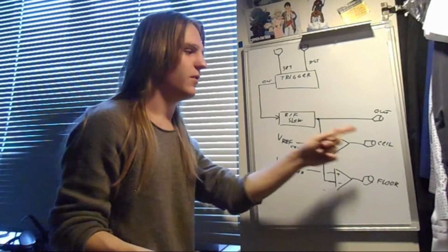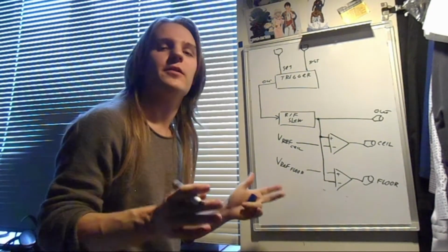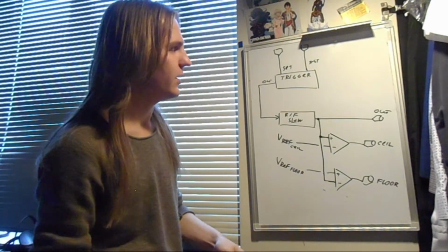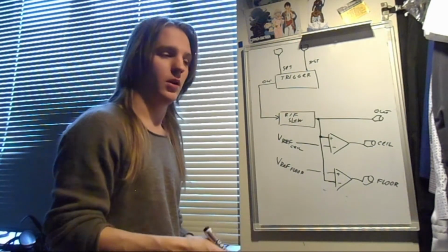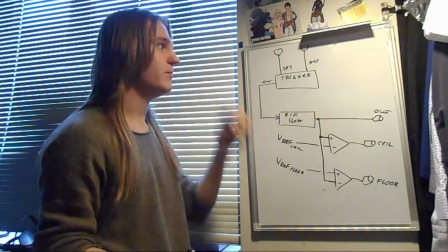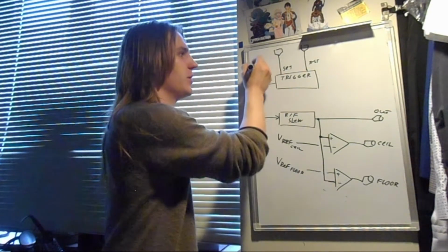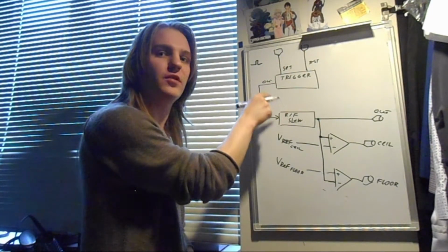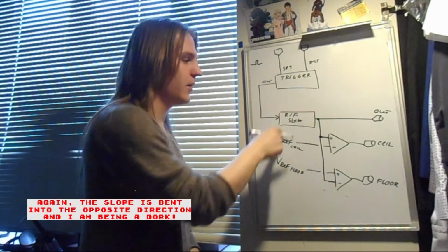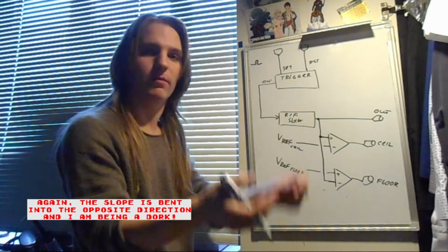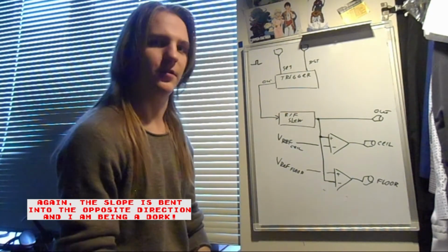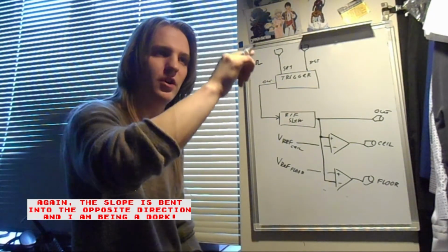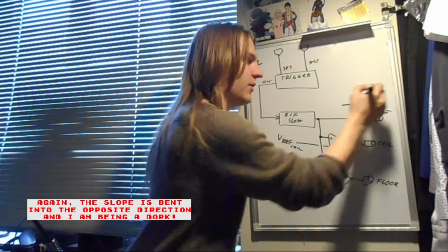Now, why would we need these outputs, and what the hell is this thing? Well, this thing can be either an envelope generator, an LFO, and many more. Imagine we have sent a short impulse into our set. This thing outputs now 8 volts, logical 1. This rise fall slew is set to very big resistances, both rise and fall. So it slowly starts charging, and the output goes like this.